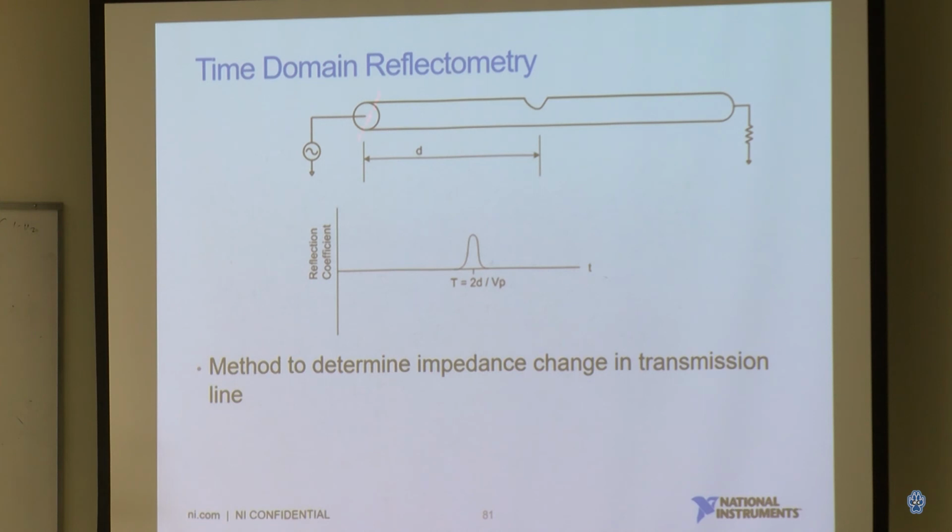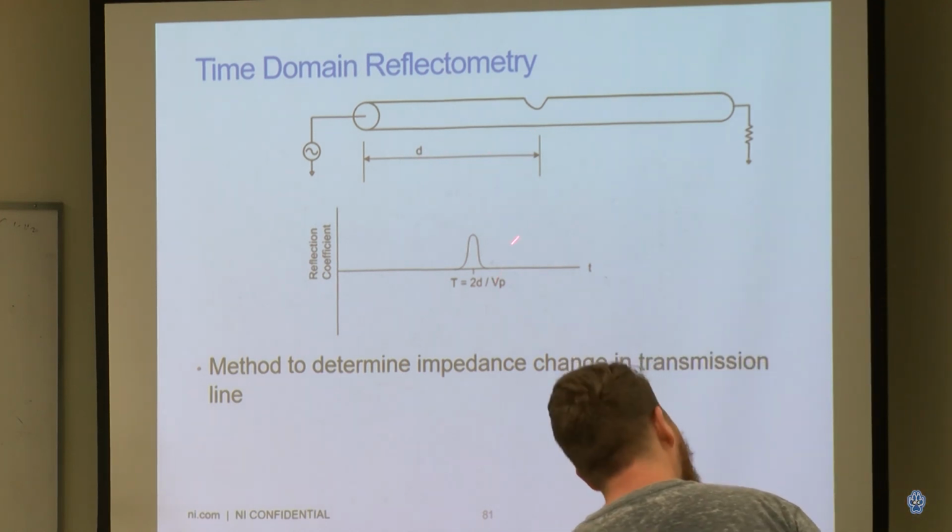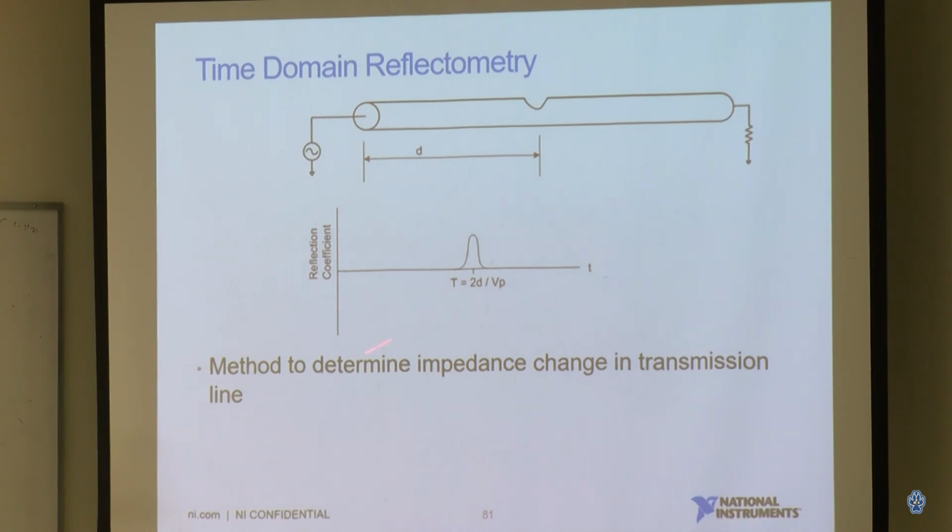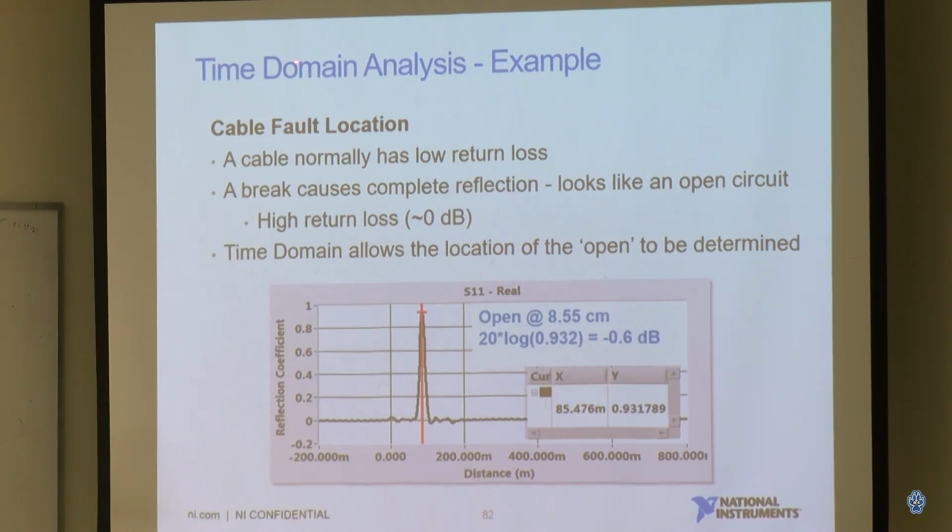And why are we using a VNA? Sometimes you can use a VNA to characterize some of the issues. Let's say you have a cable. Your cable is broken, or there is some loose wire inside in the middle, and you can use the VNA to characterize the time domain, and you see a glitch or a pulse in the time domain. That means your impedance or this transmission line is not consistently matching. Something happened in this cable. So this is why people like to use the VNA to characterize some of the hardware issues. And this is why the time domain is used.